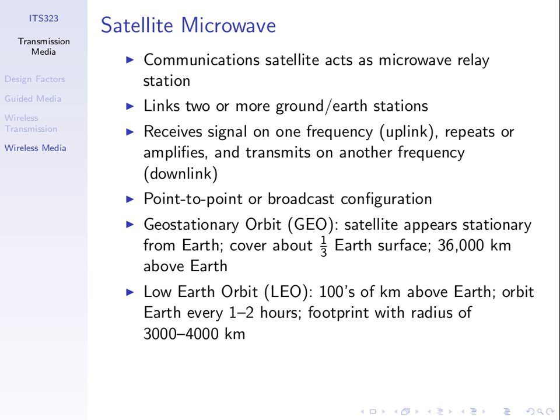That is, when I transmit up to the geostationary satellite, the signal will take 120 milliseconds to get there, and of course it needs to come down to some other ground station as well. We transmit up from one ground station to the satellite, which transmits down to another one. So up is 120, down is 120, about one quarter of a second is the propagation delay, 240 milliseconds.